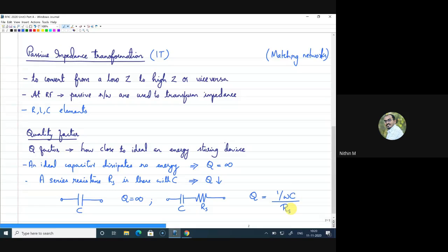Series resistance also refers to the leakage current in between the capacitor plates. Is there a question? Okay, no, Nikhil, it is not the leakage component. Probably you are referring to the dielectric leakage. No, the series resistance can be considered as a parasitic resistance that comes along with the capacitor. That is true everywhere, especially in integrated circuits. Whenever we use something called a MIM capacitor or MOM capacitor, metal insulator metal, we come across these kinds of parasitic resistance.